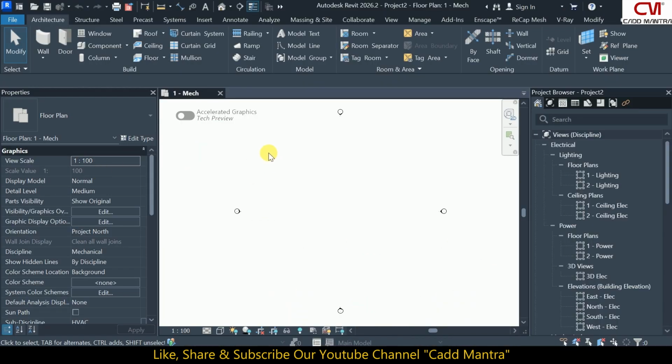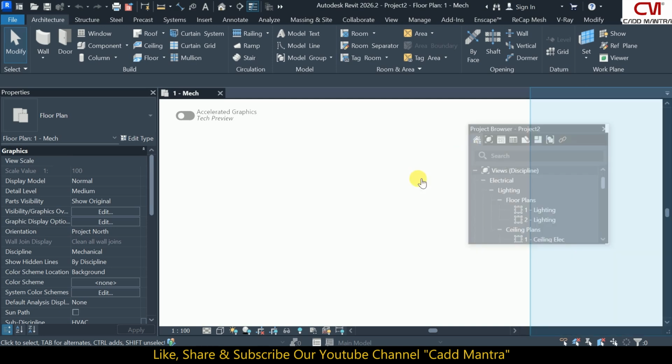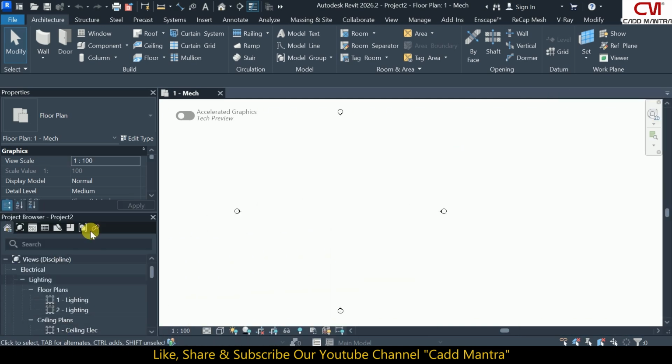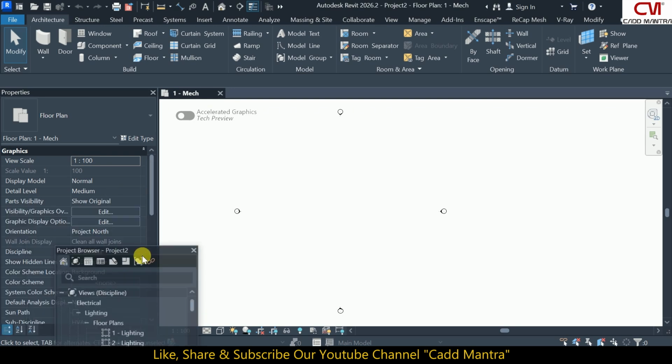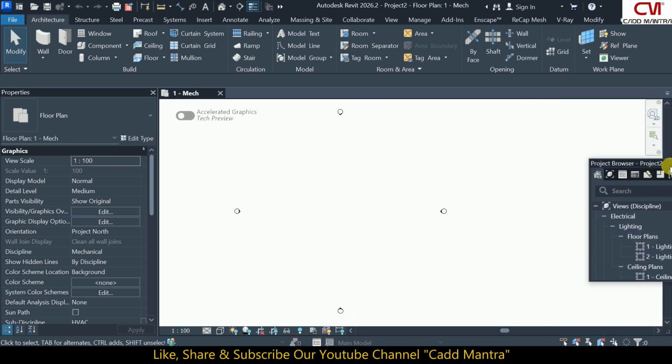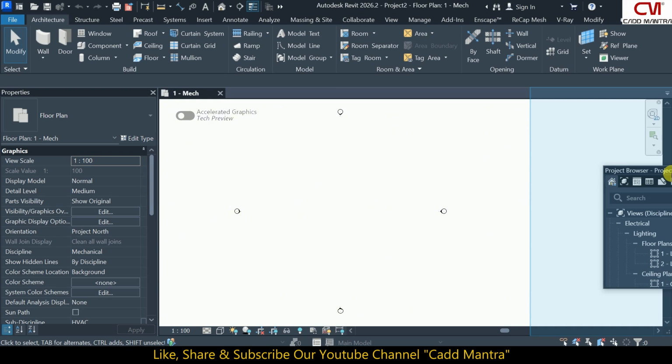This is what the software will look like, and you might find that the project browser is docked somewhere like this. Now we want the properties and the project browser to be accessible and visible on the whole. So what we will do is undock the properties browser from here and dock it to the right side like so. Make sure to go all the way to the right.